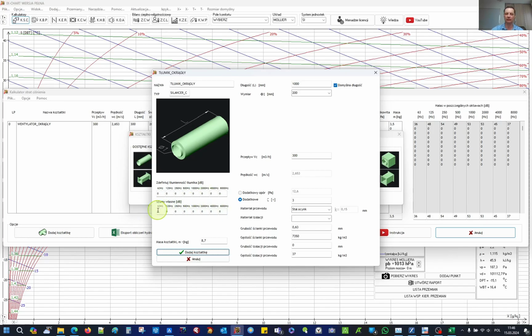Because if the manufacturer assumes that this attenuation is achieved by increasing the number of baffles, then within the silencer the head-on airflow speed increases, and this speed causes self-noise to occur, and therefore a good silencer manufacturer should always provide these two values simultaneously, so that it does not happen that we choose a silencer with very good soundproofing, but it ultimately has enormous self-noise and can sometimes generate more noise than its soundproofing level, which is why this should also be taken into consideration.